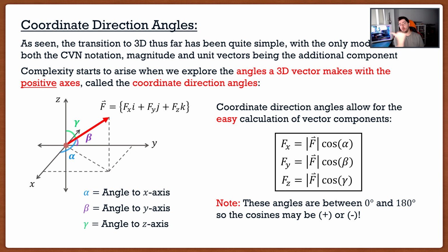So let's say that I had an axis that is positive going to the right, but my force vector is actually going to the left. Well, as we can see here, the angle is going to be greater than 90 degrees. So let's say it's 120 degrees. If I take the cosine of 120 degrees, I'm going to get a negative value. So this math actually takes into account direction, because if my angle is greater than 90 degrees, it'll automatically become negative, which indicates it's going in the opposite direction. So it's really nice for us because this allows for those negative components.